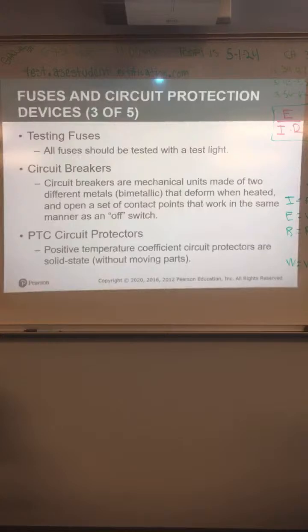Gotcha. Circuit breakers, what is a circuit breaker? Isn't that where it cuts off power if something's going wrong along the way? Yep. Basically, what happens is they're made of these bimetallic metals that deform when they're heated. So what it does, it opens the circuit. Sometimes when they cool off, they will automatically close the circuit again. Kind of works as an off switch. The positive temperature coefficient circuit protectors are solid state without moving parts.